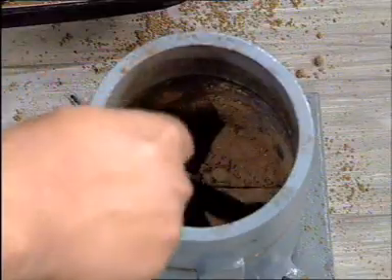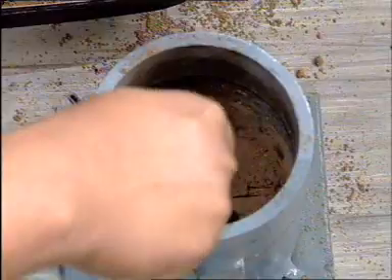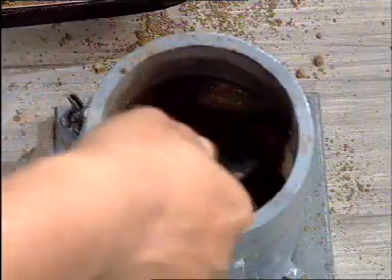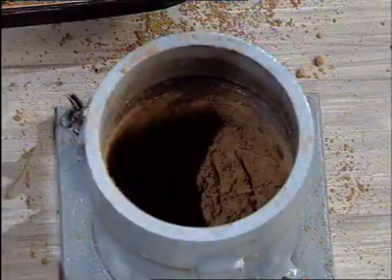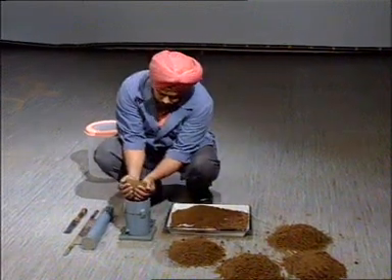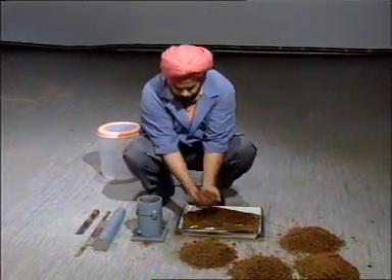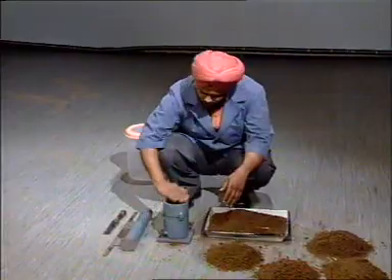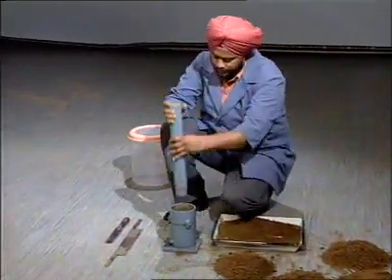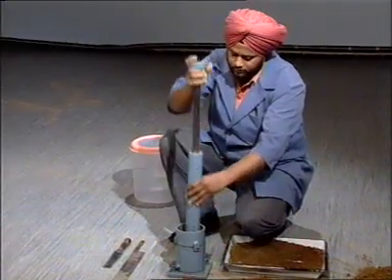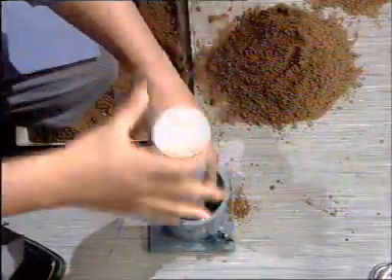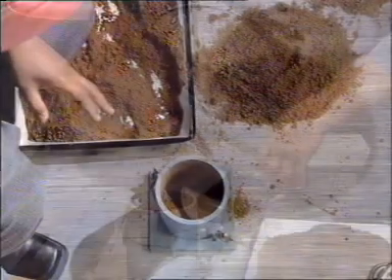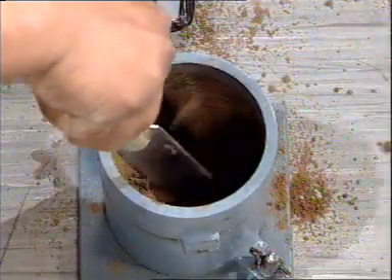Scratch the top surface of this layer with the help of a spatula. Now place the second layer on this compacted layer. Again impart 25 blows uniformly distributed to this layer in the same manner. Now again scratch the top surface of this layer.